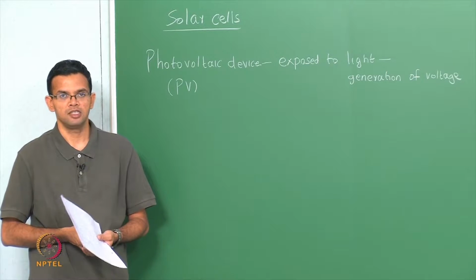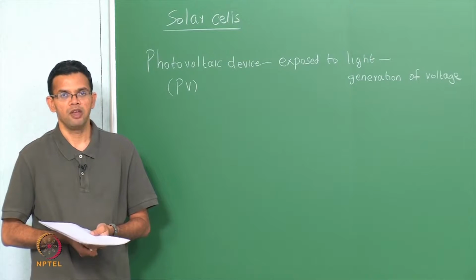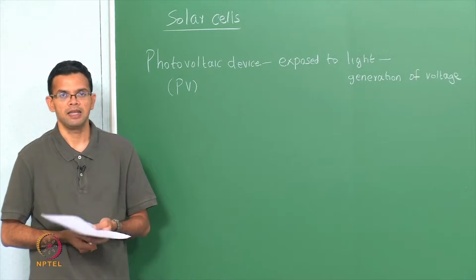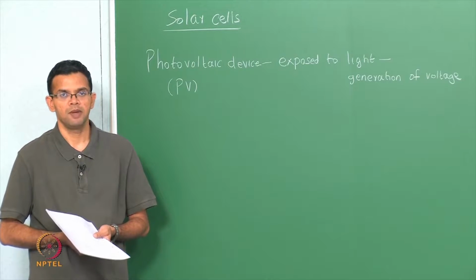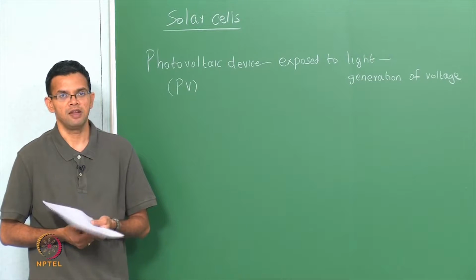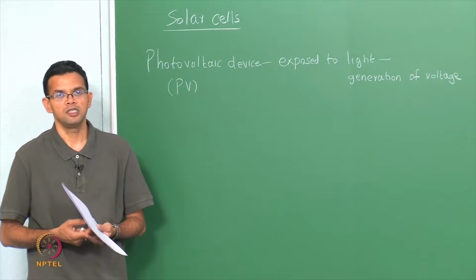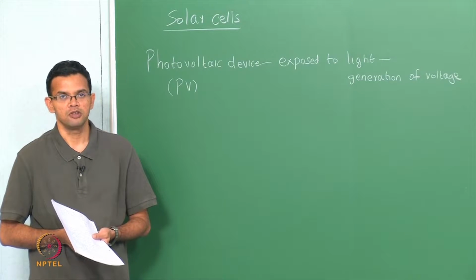So if there was a transition from the valence band to the conduction band, the maximum wavelength was defined by the band gap of the material. The minimum wavelength range depended upon the absorbance of the material, because as wavelength decreases, absorbance increases, so that light is only absorbed very close to the surface.